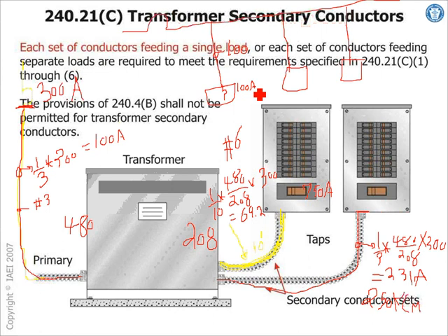It doesn't say a conduit. Approved manner could be on the top of the pole. That's protection. And the conductors terminate in a single breaker or single circuit breaker that limits the load to the capacity of the conductor, made to supply a number of additional overcurrent protection devices. The overcurrent protection device for the conductor is an integral part of the disconnect. The disconnecting means for the conductor is installed in a readily accessible location outside of the building. So as long as all this is outside the building, go tap as many as you want.